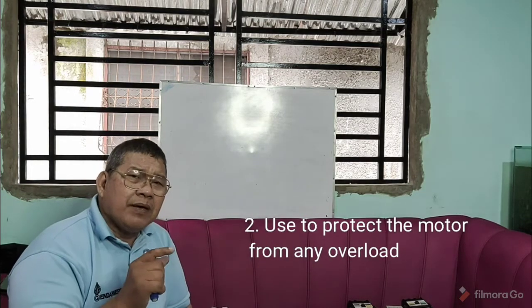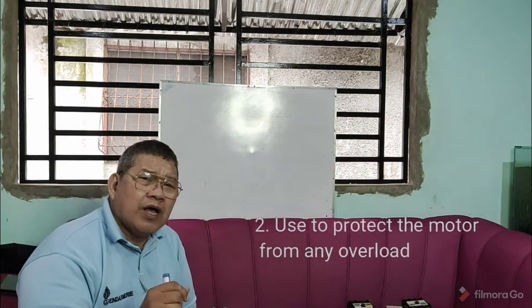Now remember, a certain motor has its own amperage or ampacity. Meaning to say, there is a full load current. If you will be driving this motor more than its capacity, then there's a tendency that the motor might be overloaded. Then the motor will become defective. So in order to prevent this, then we will again be using this magnetic starter.